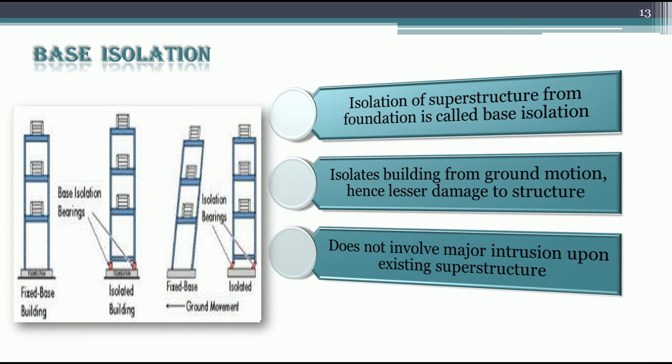Next retrofitting technique is the base isolation. Isolation of superstructure from the foundation is called base isolation. Superstructure is the structure above the ground level, and foundation or substructure is the structure below the ground level. It isolates the building from ground motion, hence lesser damage to the structure.